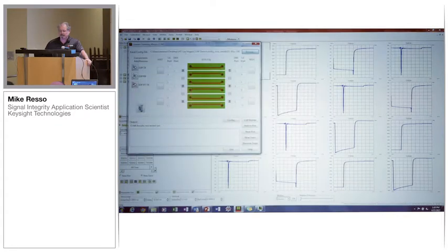And then here is a graphical representation of my 3 differential channels, the 12-port measurement. And I'm going to drop a differential transmitter on the victim and a differential receiver on the victim. And then I've got these differential crosstalk terms that generate crosstalk.